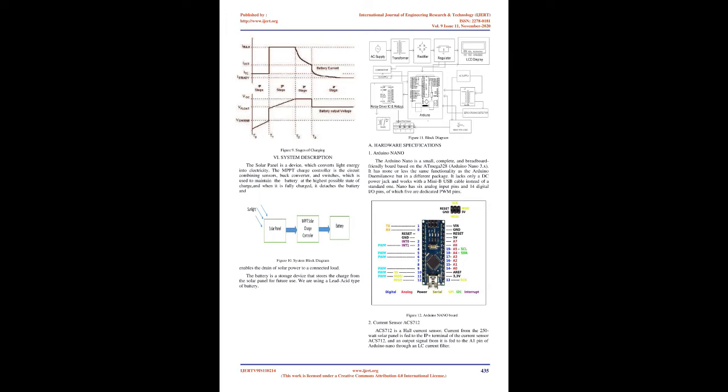As shown in the figure below, the constant current mode is used at the beginning of charging. Since the battery accepts higher current when the battery is low, most of the energy released can be quickly replenished. This mode continues until the battery voltage reaches the set voltage, and then the charger switches to the constant voltage mode to continue charging. At this time, it is called the equalization mode. After the battery is fully charged, the charger automatically switches to the floating mode to keep the battery fully charged. D. Pulse charging method.